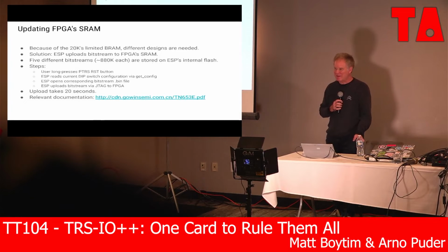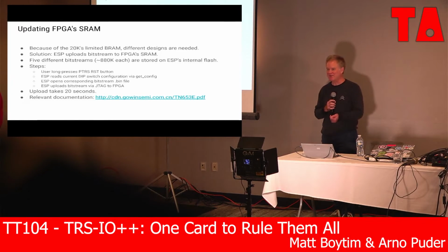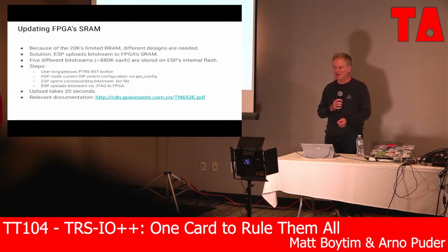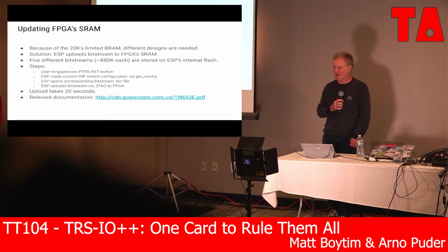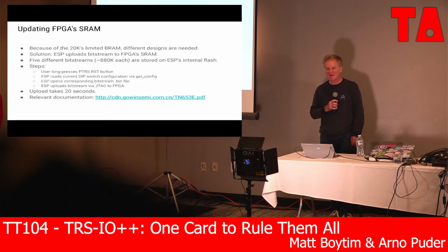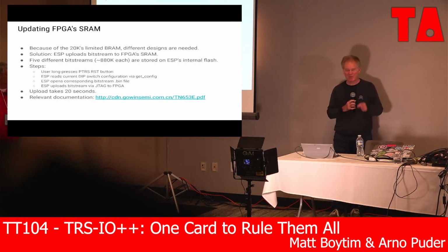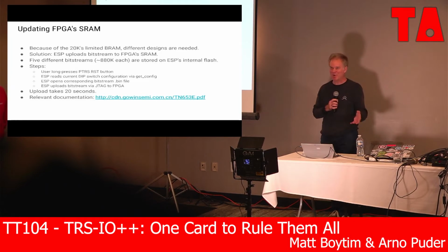Which also means that if you switch modes, then the ESP has to update the FPGA. And that is one thing that I contributed. So using JTAG, there's a way. JTAG, I knew it only as an acronym, and I learned a lot more than I ever planned to learn about it. But you can do a lot with JTAG, and one of those things is that you can upload bit streams to the FPGA. With the documentation mentioned on the bottom, that is how I managed to reverse engineer it.